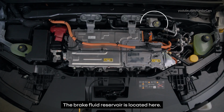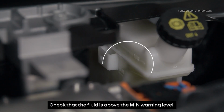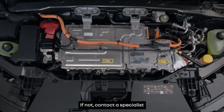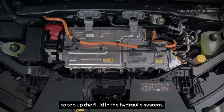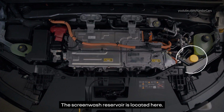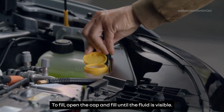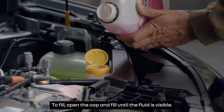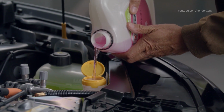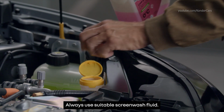The brake fluid reservoir is located here. Check that the fluid is above the min warning level. If not, contact a specialist to top up the fluid in the hydraulic system. The screen wash reservoir is located here. To fill, open the cap and fill until the fluid is visible. Always use suitable screen wash fluid.